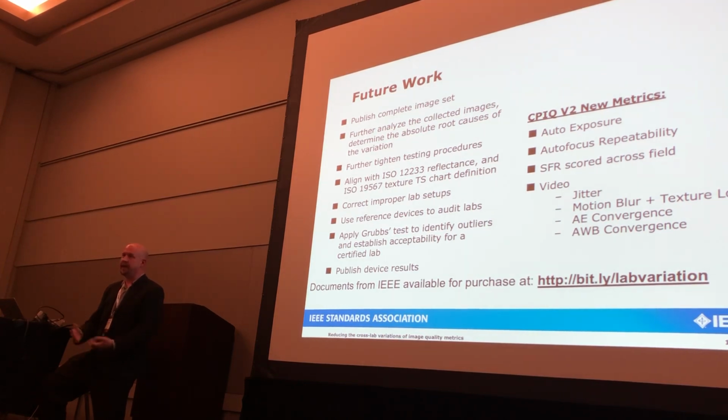So we put a card in front of the camera and focus on that and then pull it away. Okay, so an occlusion to the optical path. Yeah, and I think it's better to be a card with spatial contents on it, because if it's a diffuse card, the phase detection autofocus gets very confused. The laser focus goes to close distances, is not confused, but it doesn't really treat those two systems equally.